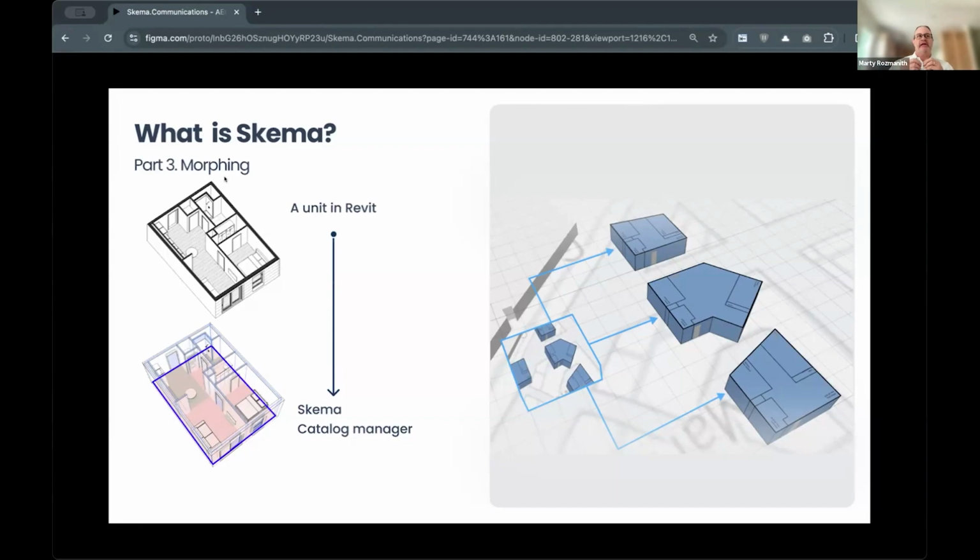And whatever extensions you made to the properties, whether type or instance properties in those things in the model, you're going to see them when we put them back out into Revit, because we're storing a binary blob of that definition. When we write it back out to a Revit file, it's going to have anything you've put into that type or instance definition that we captured when we brought it into the assembly, stored in Schema. So that's another big thing that makes us different than some other solutions.